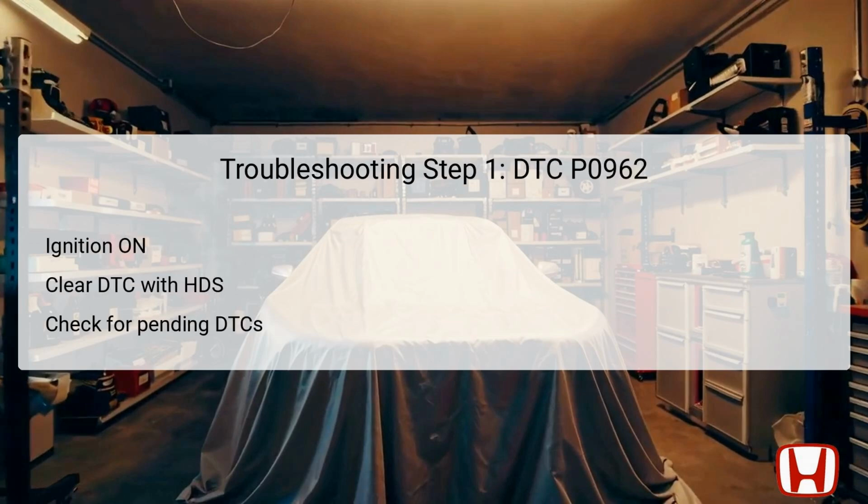In the first troubleshooting step, begin by turning the ignition switch to the on position or pressing the engine start-stop button to select on. This allows the vehicle's onboard diagnostic system to be accessed. Next, clear any existing diagnostic trouble codes, DTCs, using the HDS, Honda Diagnostic System.